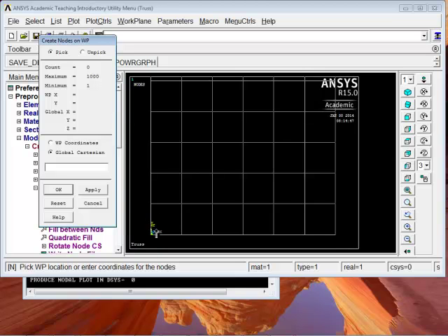We're going to start with the one at the bottom left-hand corner because that's node number 1 on the sheet. Just click with that arrow pointing up like this. Click right on that corner. You can see count number 1, minimum 1. So that's 1.